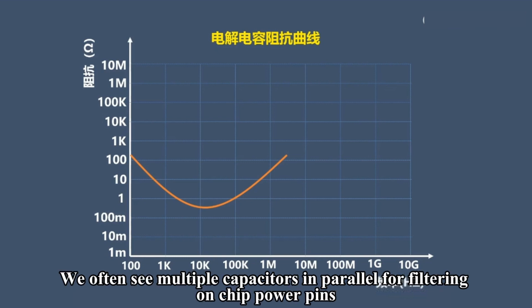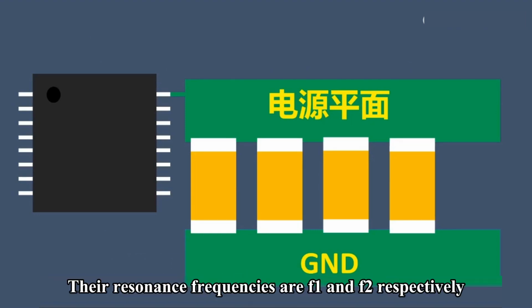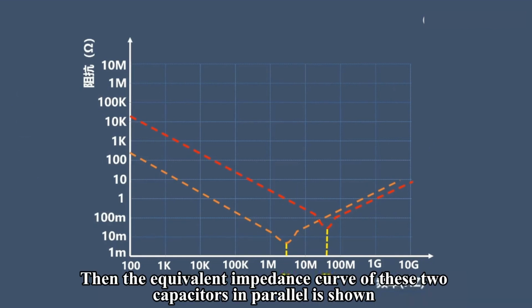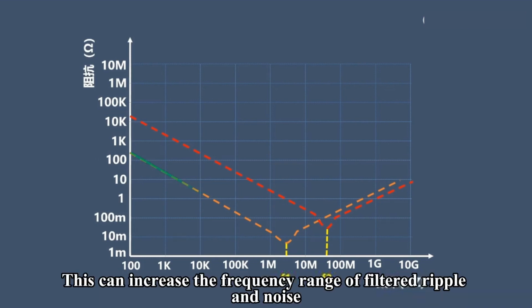We often see multiple capacitors in parallel for filtering on chip power pins. For example, there are two capacitors with dashed impedance curves in parallel. Their resonance frequencies are F1 and F2 respectively. Then the equivalent impedance curve of these two capacitors in parallel is shown by solid lines with two relatively low impedance points. This can increase the frequency range of filtered ripple and noise.